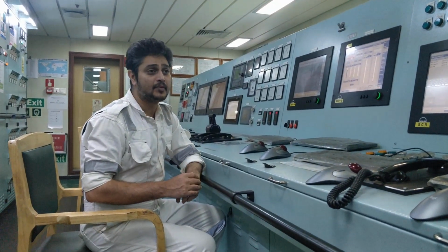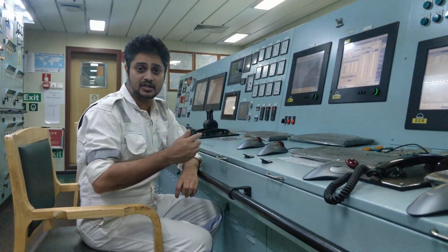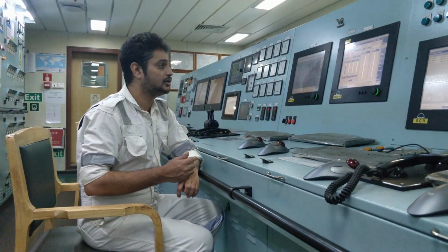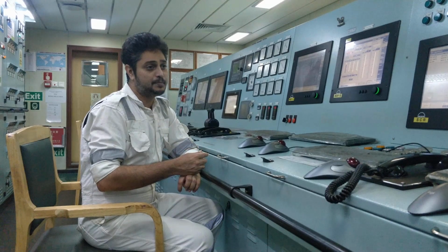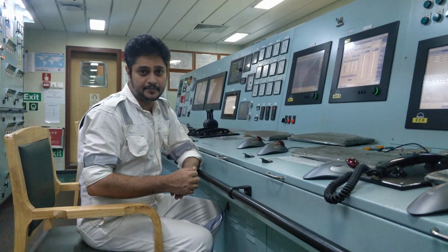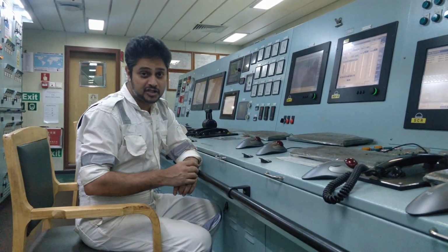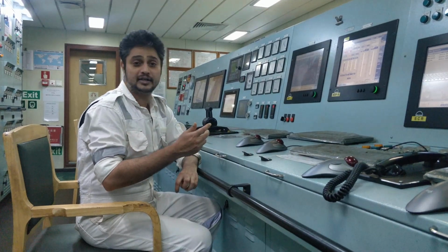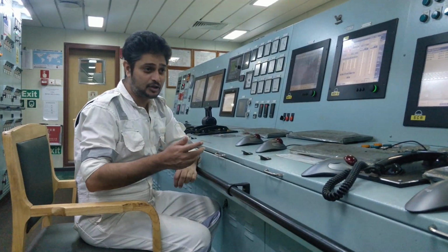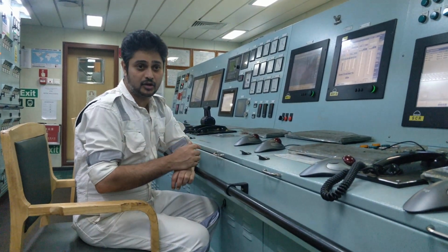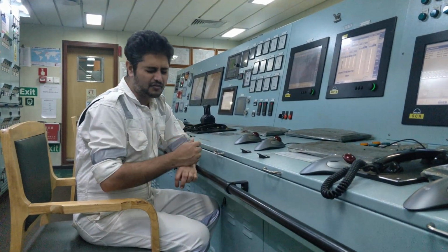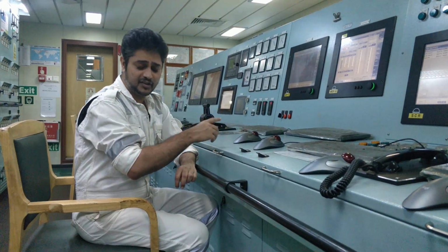The next thing is the HPS system. When the engine is getting reversed, the direction of the pump rotation also changes, since it is engine driven. The HPS pumps are variable displacement type, so the suction and discharge ports remain the same. Only the pump swash plate position changes. HPS is controlled by the ACU. As I told you before, once the ECU gets the reverse order in the telegraph, it sends a signal to both the CCU and ACU.